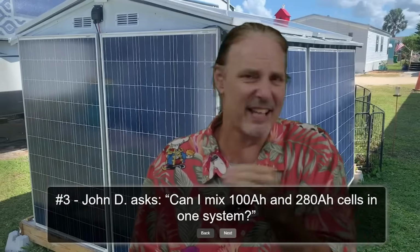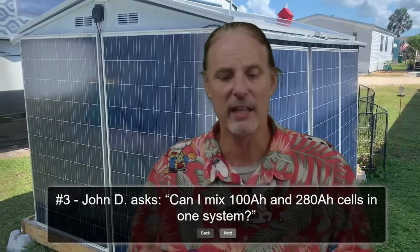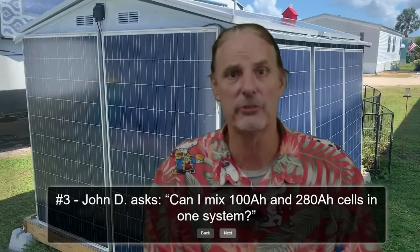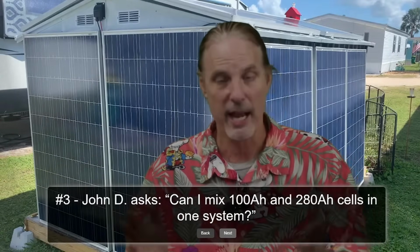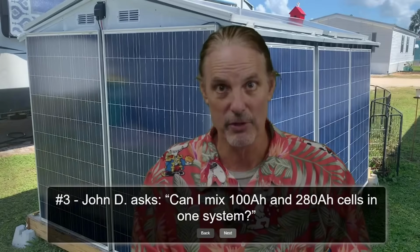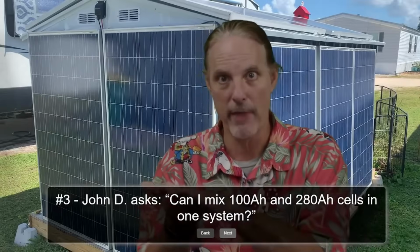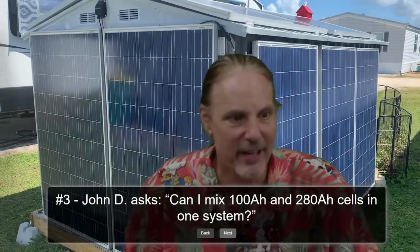I see it all the time when I turn off my JK BMS to validate the torque on all the battery cells and make sure that they're all okay. When I turn it back on, I'll see some 20 or 30 amps flow from it to the 3 EG4 batteries. That happens quite frequently, but if I had it off for any length of time, then I would make sure that I waited for the EG4 batteries to gain the charge back to where that battery is before I turned it back on. So that is my suggestion there.